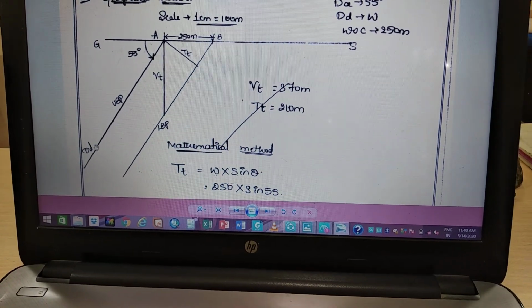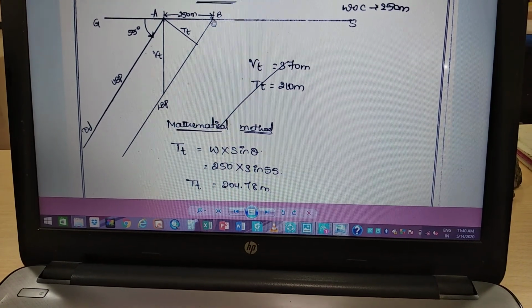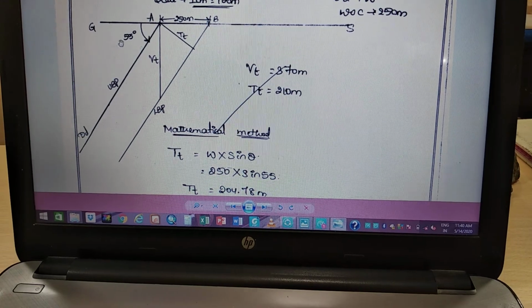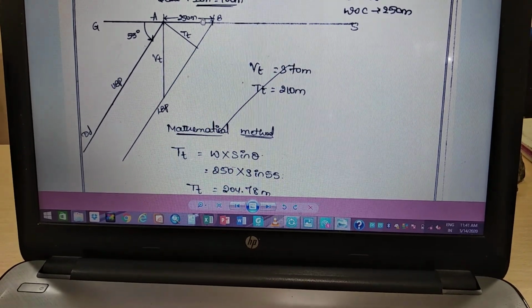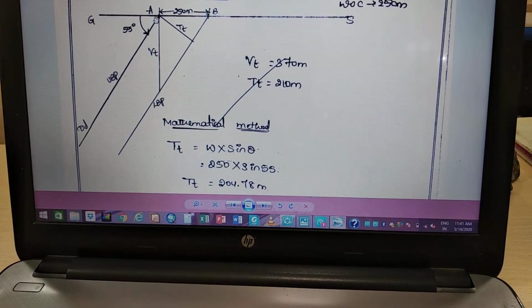And draw this upper bedding plane, and parallel to this draw this another contact, that's called the lower bedding plane. So you got dip direction and dip amount also. So we got the width of the outcrop. So we need to calculate the vertical thickness and true thickness.